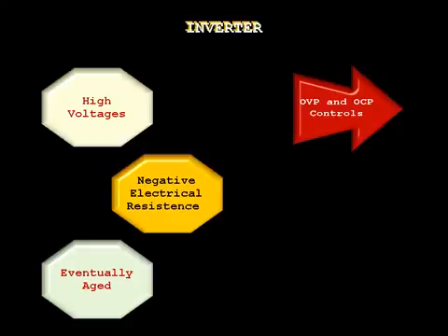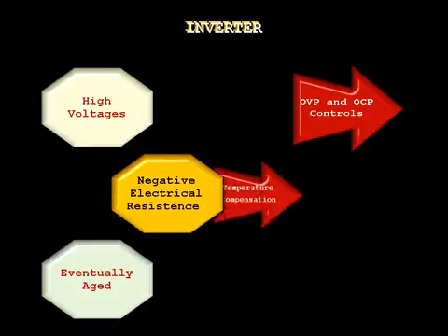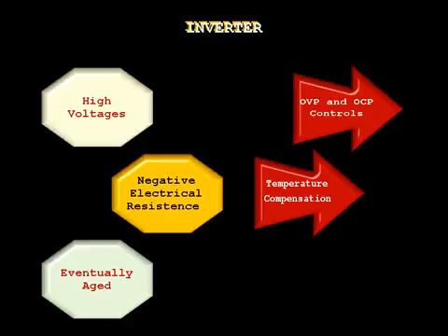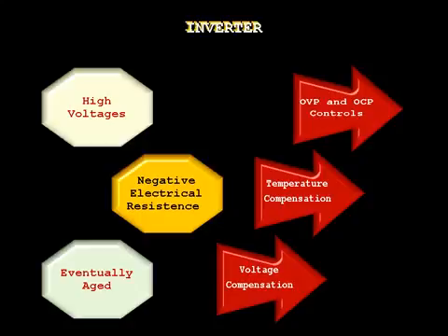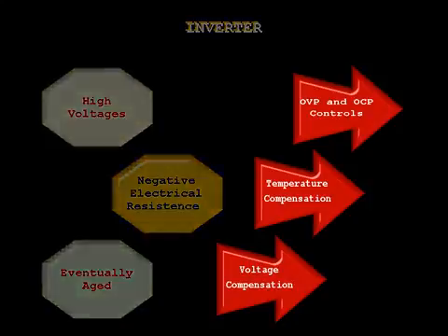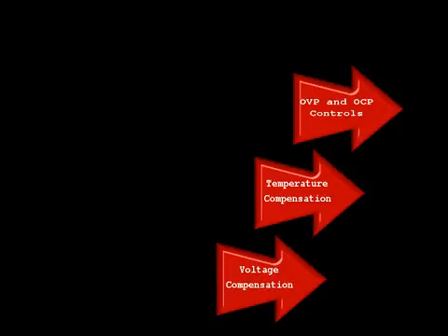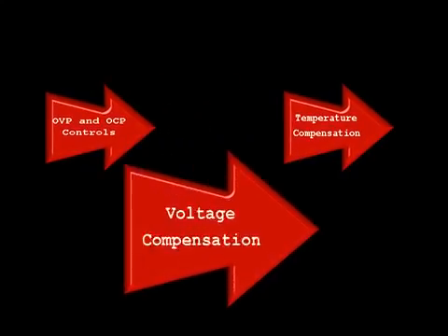Since they conduct more as they heat, the voltage must decrease at some point to avoid the lamp's explosion. So, it is necessary to have circuits that control the amount of voltage. And the inverter begins to operate in an intermittent way or simply shuts down if it cannot balance the brightness of a lamp assembly, since they gradually lose efficiency. It means that we have to add to the oscillator, the transistor and the transformer some circuits that control and watch over for a precise measure, so that nothing be left apart.